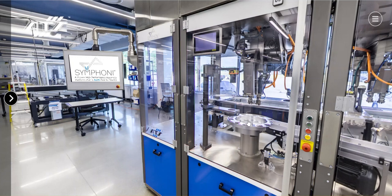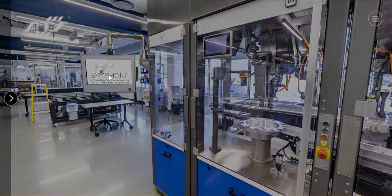Another thing that you can do from the HMI is select what rate you want to run at. One of the characteristics of Symphony is that it operates in a synchronous fashion. So even though it is digital, even though it is highly flexible, when it operates as a system, all motions in the system are completely coordinated as if they were all mechanically geared together. In fact, they are geared together. It just so happens that they are electronically geared together. And that allows us to do some interesting things like what I'm going to show in the video here.